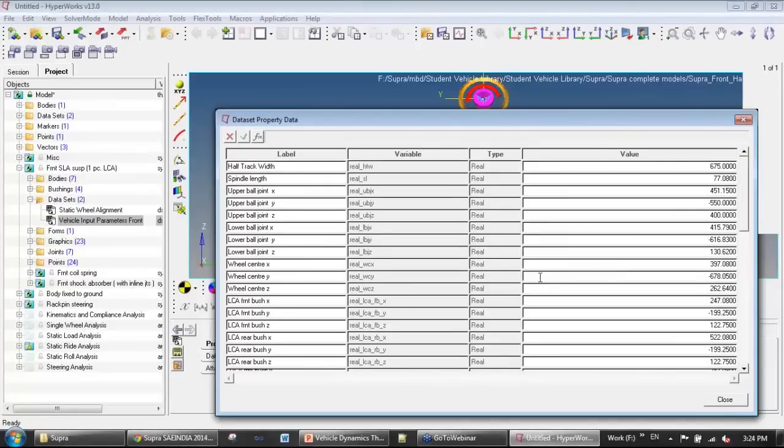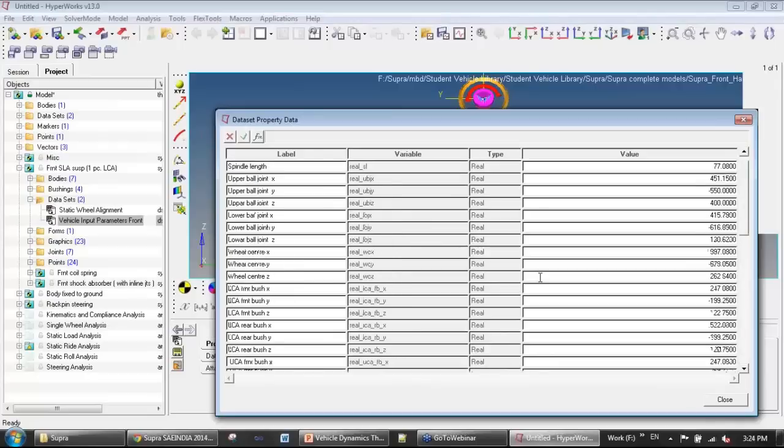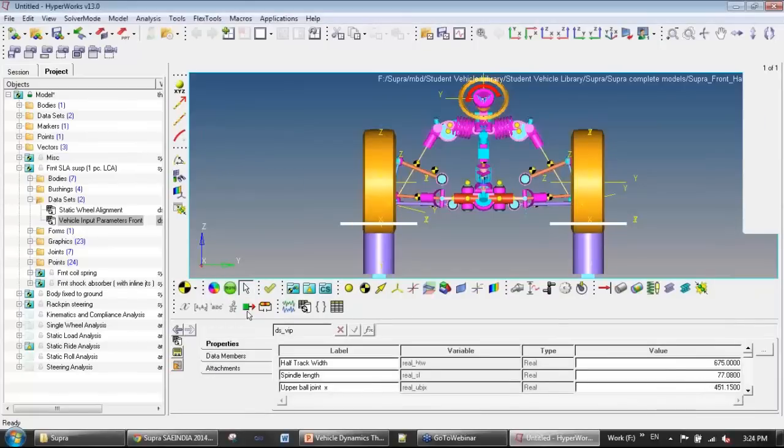It is highly recommended that you only change points from this table and not from the points area directly without doing the advanced motion view tutorials. These should be enough for you to iterate through basic suspension design and multiple configurations.